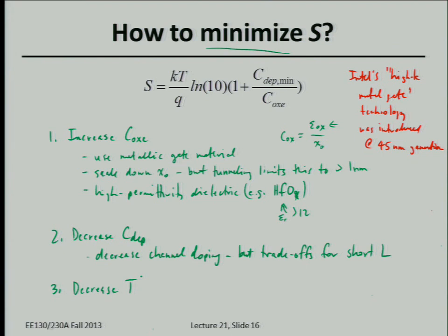Goes up, right? Okay, but it doesn't go up as fast. I mean, it's not directly linearly proportional to temperature. So overall, yes, it does improve the subthreshold swing. So this allows you to design your transistor to operate with lower threshold voltage. So that's very good. It turns out that mobility also is dominated by lattice scattering, and so if you lower the temperature, this is also good